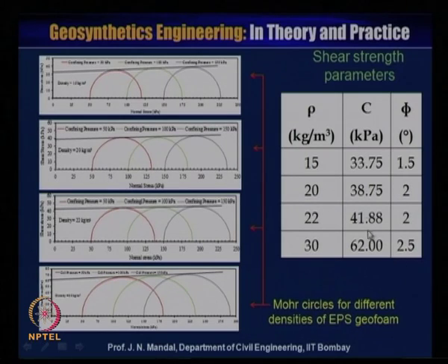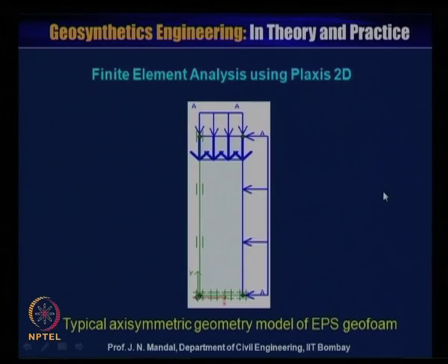You can see there is an improvement of the C value with increasing the density of the geofoam material, but the phi value is not improving significantly. That is, the angle of shearing resistance is not improving much.